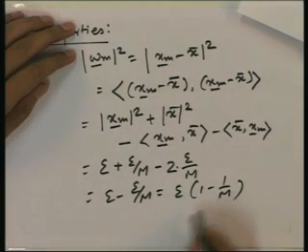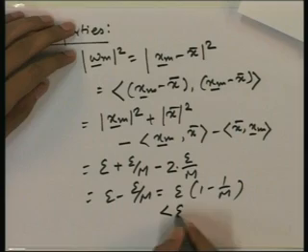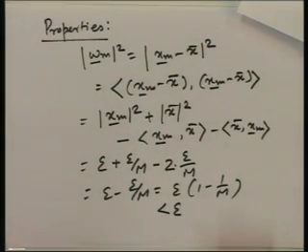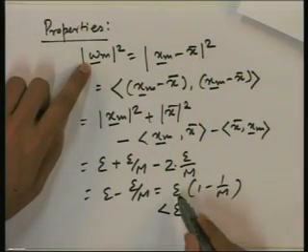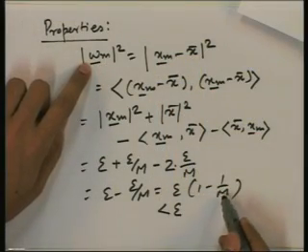Now, as you can see, this is less than E. This is something interesting. It shows that all the signal points in the simplex signal set have the same energy, but it is less than the energy of the orthogonal signal set, which was E. For the simplex signal set, the energy of each signal is E times 1 minus 1 by m.